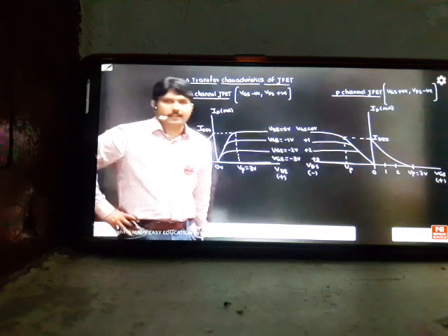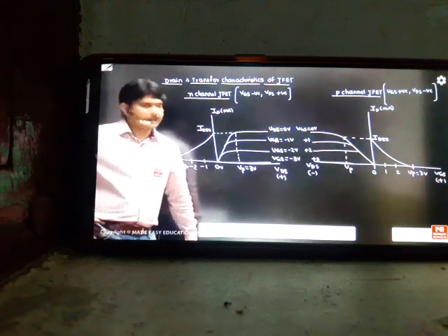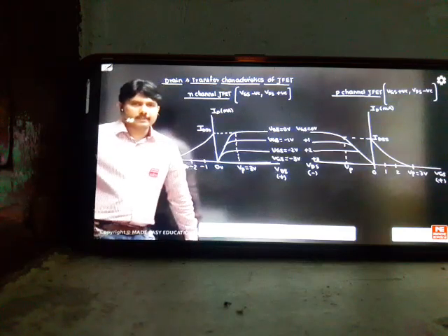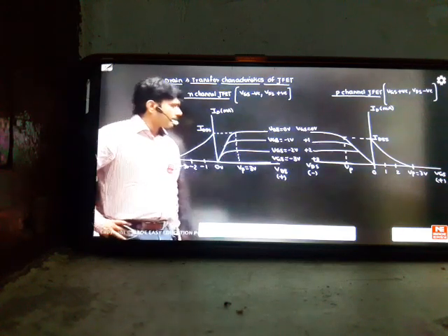Yes, Pandit, that only I'll explain you. Please give me the time for it. How the current will decrease, we have to see now. If you see here, the current is decreasing actually as the VGS is increasing. In reverse bias, minus 1, minus 2, minus 3, the current is decreasing like this. The behavior I'll explain you.